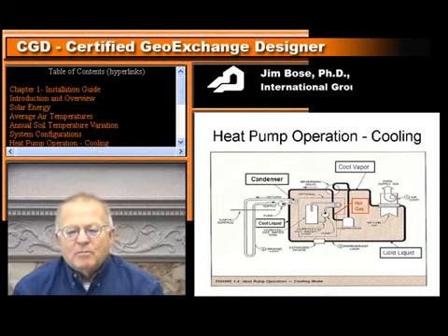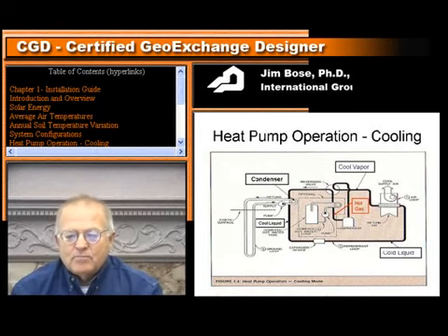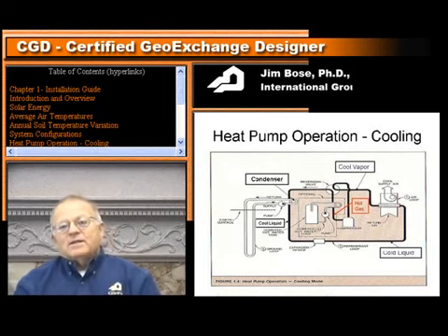Now, the heat pump operation is just a lot of fun. You have a refrigerant that's being circulated by a compressor. It is a piston compressor or a scroll compressor. It could be a centrifugal compressor. It could be any kind of refrigerant compressor that's compressing the refrigerant vapor. So whatever comes into the compressor will be a vapor, and the compressor then compresses that, and in the process